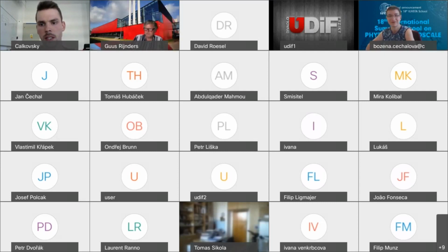There are trends to avoid using piezoelectric materials containing plumbum. Have you considered to involve lithium niobate or other piezoelectric materials in your MEMS? Sure. Actually, again, I did not have time, but we do quite a lot on different materials also. Potassium niobates and lithium niobates and other compositions, but also aluminum nitride, but then mainly the scandium doped aluminum nitrides. That is a material that shows very interesting properties, and it can be grown quite easily with pulsed laser deposition. And there, the scandium doping is quite important. And there, the PLD process is a bit different from sputter deposition. And at least we have shown that we can do this already on small scale PLD systems, but also at large scale systems already.